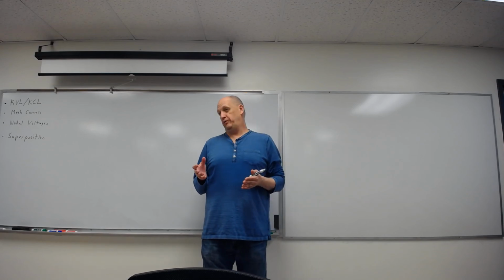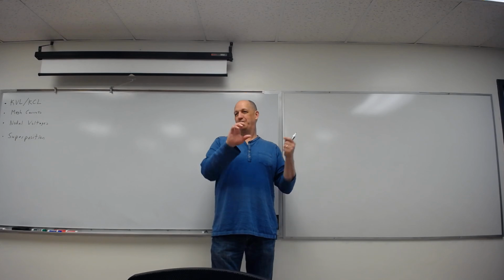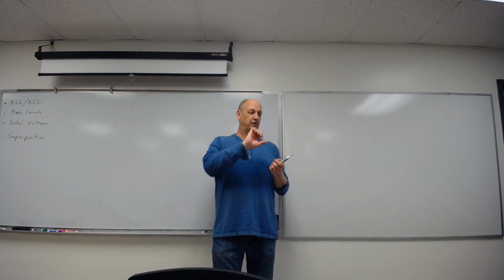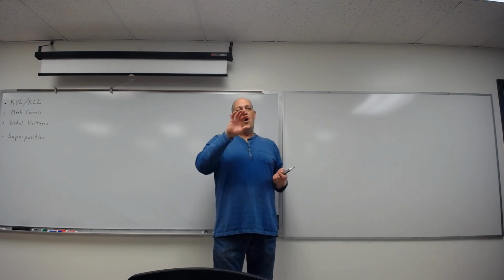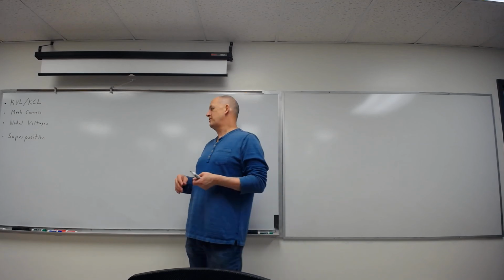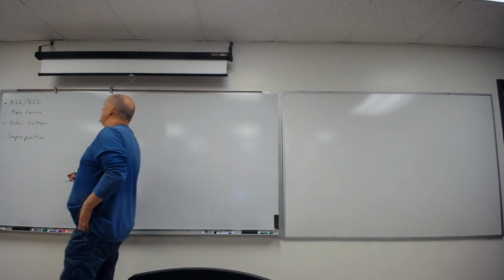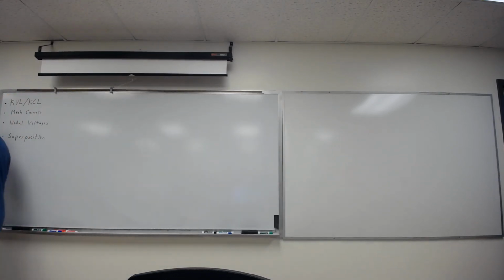That's why you have to turn both. You have to turn both up, though. You notice if you just turn voltage up and current all the way down, it won't do anything. You turn the current up, it'll limit what the current will be, and then you adjust the voltage. Or you turn the voltage up, and then it'll limit the current, but allow the current to go to a certain point.